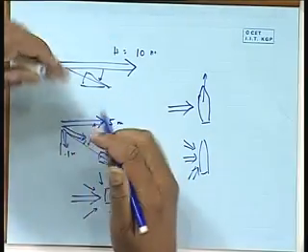So what happens is that when you assume that the waves are not from one side but from all sides coming, then you have got a different kind of response. It is normally mellowed down, like it is spread. So this is how we can find out motion in a three-dimensional spectrum. It turns out that most motions in a three-dimensional spectrum would be lower than the corresponding maximum you might get from one side.